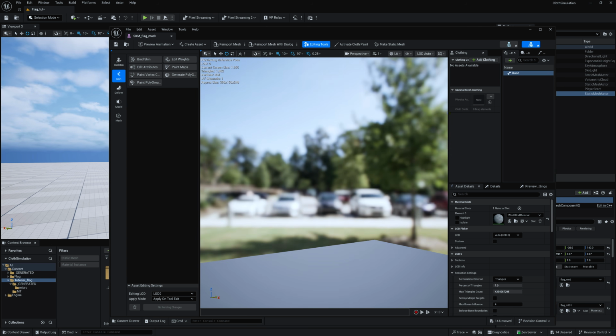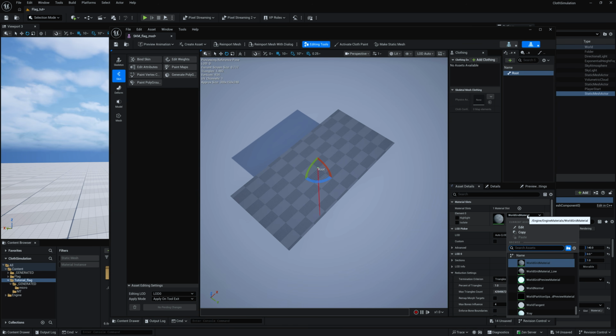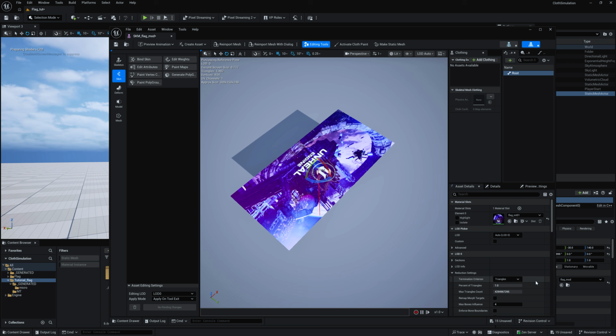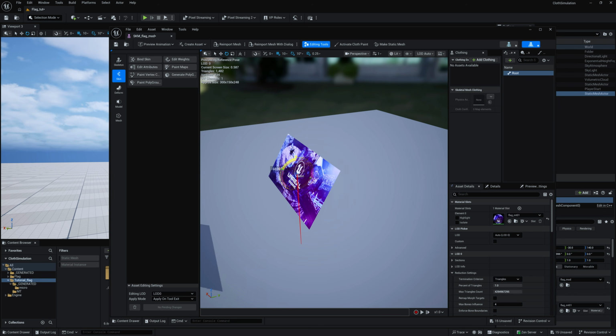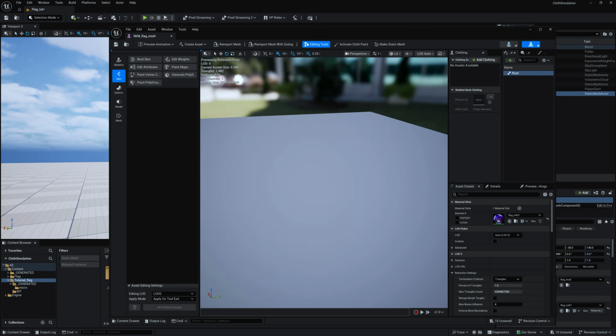you can apply the material here as well. Now by default it will apply, but maybe some glitch in the new version, so that's why it's not applying. So you need to reapply this. So simply type flag01 material. So now as you can see, this is already applied. Now simply rotate this to, let's say, 90 degrees, and now your flag is here.